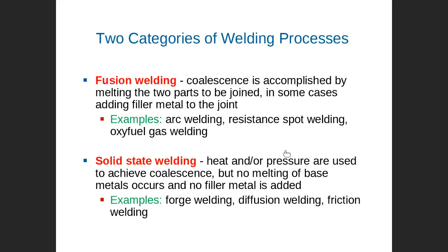To remind you, in welding generally we have fusion welding and solid state welding. I believe you understand what that means. Fusion welding is liquid state welding, meaning we melt the welding zone of both substrate materials. You get a liquid mix, and after solidification the weld is done. Solid state welding has no melting at all. It's cold welding. Probably we can heat also, but less than melting temperature, usually 0.5 of the melting temperature or something, just to activate or encourage the atoms to migrate from one material to the other. Then a bond will be created, then the weld will be done.